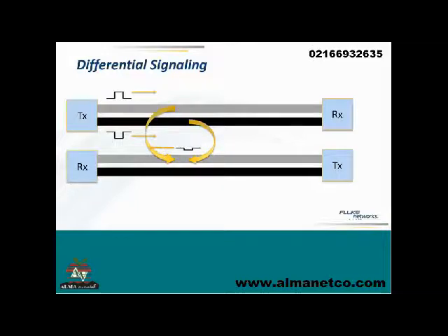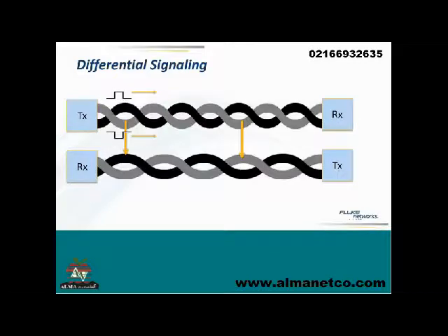But not entirely, because if you look at my picture here, you'll see that the black wire is a little closer to the gray wire below it, and so it picks up a little bit stronger signal from the black wire, the bottom cable, than it would from the gray wire. And that means you're still going to get some crosstalk there. Even though it's been greatly reduced, there's still some. So how do we get rid of that? And this is where it's like, really, that's how they do it?